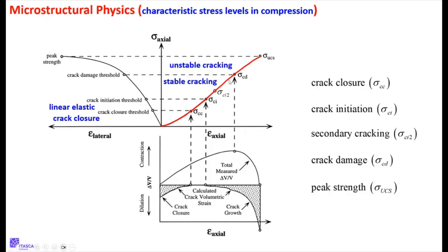So if your stress is up to here, yes, there's a bunch of cracks in the wall of the excavation, but that's fine. It's just a lower safety factor, and we're willing to live with that if we're doing mining. But we want to have a higher safety factor if we're going to have the public in there, like in a subway. Okay, with me? Make sense?